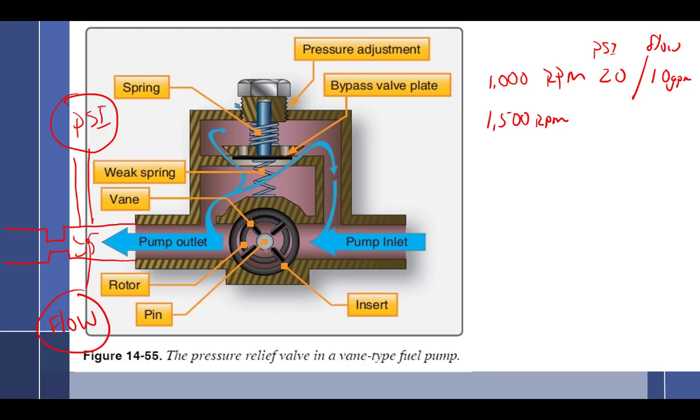Yes. Remember, a pump pumps volume, not pressure, especially this type of pump. So volume's going to go up. What's it going to go up to? I don't know, it just goes up some. But let's take a look right here. What is my PSI going to go to? I've sped up the pump. We've all agreed the pump is putting out more volume right here in this area.